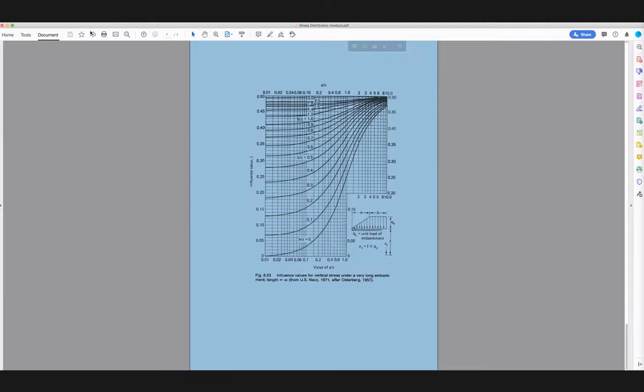What would you do if we were considering an embankment built on a slope? If it's important, if you really needed good numbers, you would probably go to a technique beyond something that is in a chart solution like this, such as finite element analysis. I would expect you could probably simplify the geometry to make it work here and get a good estimate.